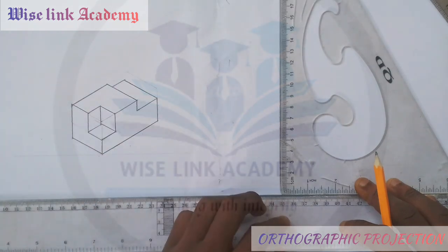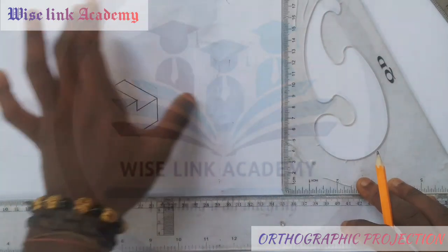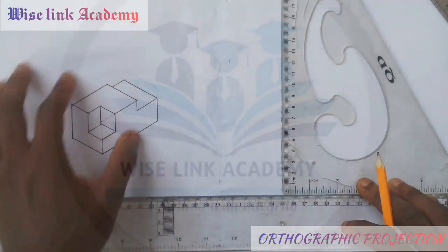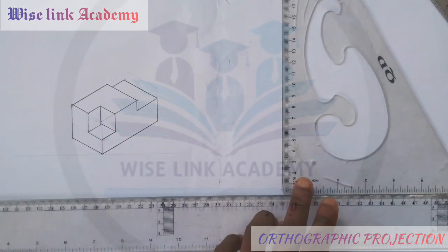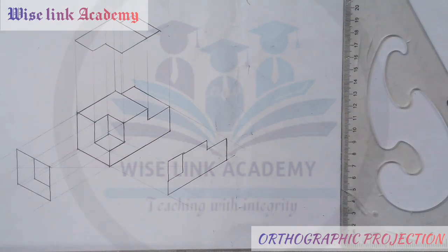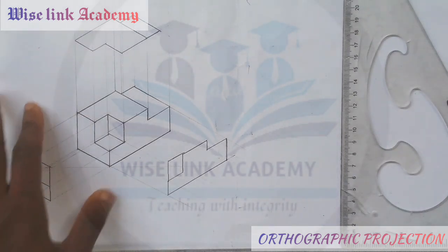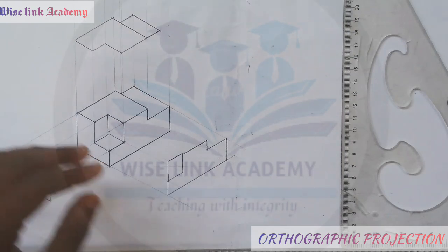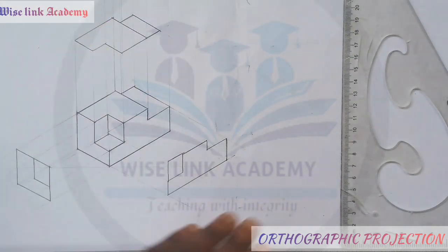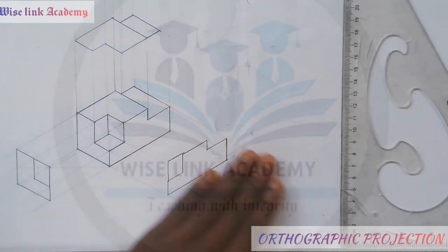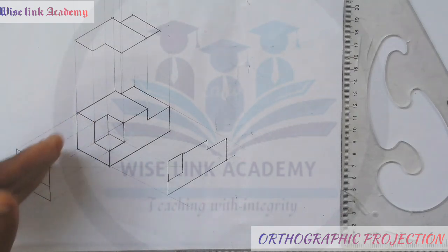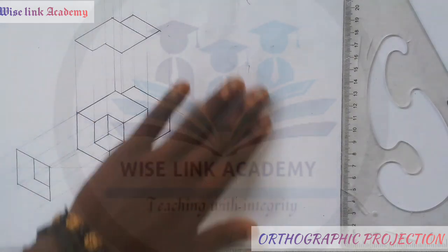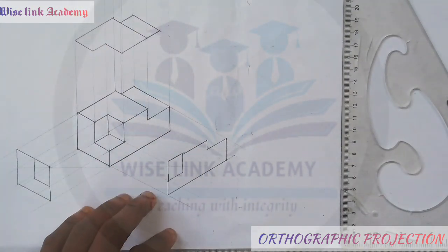Before I do that, let me show you how the orthographic of this will look. This is what we'll be seeing, right? If I'm told to draw the graphic, what I'll be seeing is the plan, the elevation here, and this end view, or you call it the side view. Now, if I want to draw the orthographic of this, what do I do first?